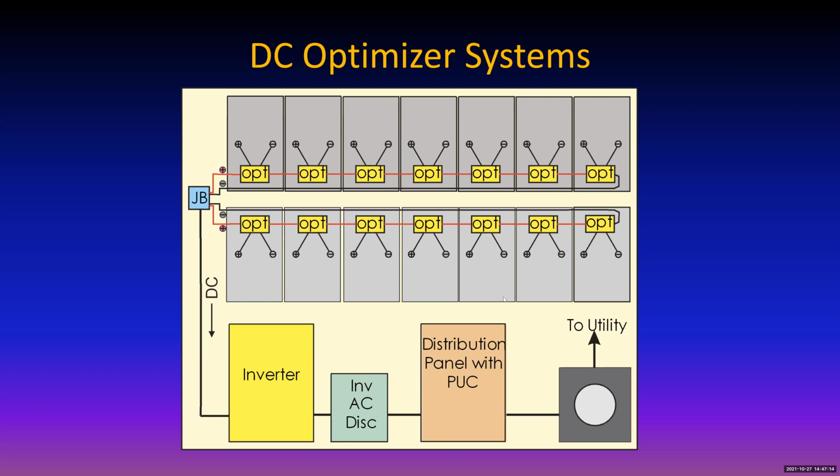Let's see, Sobrato, which of the two configurations are more commonly installed? I can tell you of the some 1,400 installations I've worked on, about 90% of them are microinverters, and about 10% of them are optimizers, and about 0% of them now are straight grid connect. The straight grid connect is the way it's done with the huge systems where there's little possibility of shading, like that industrial system. So if we were doing utility scale, then we would not probably be using optimizers or microinverters.